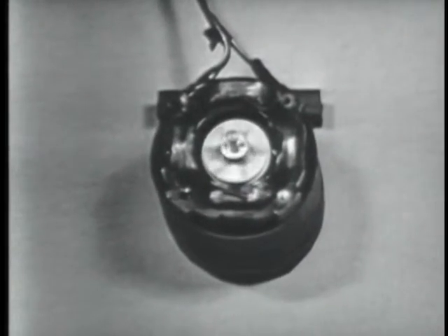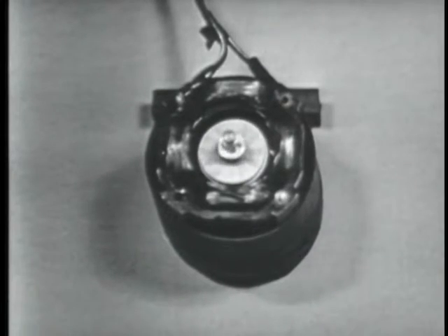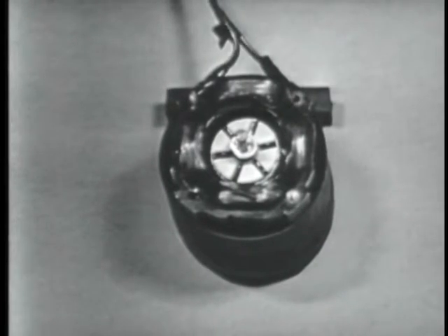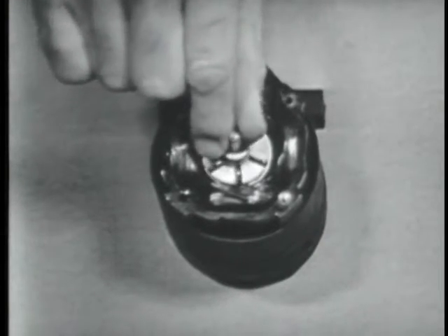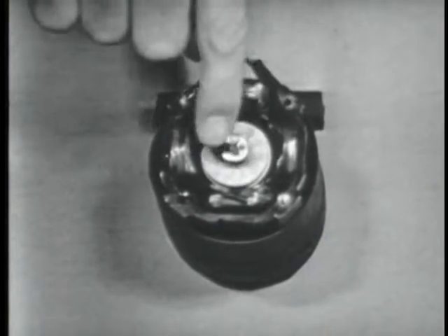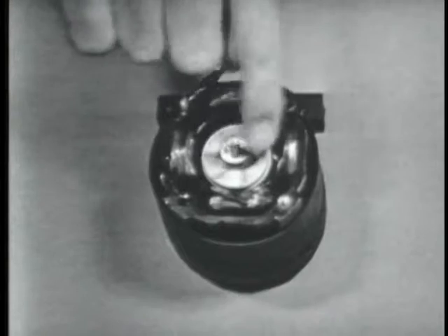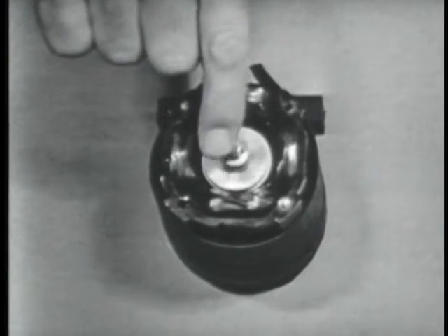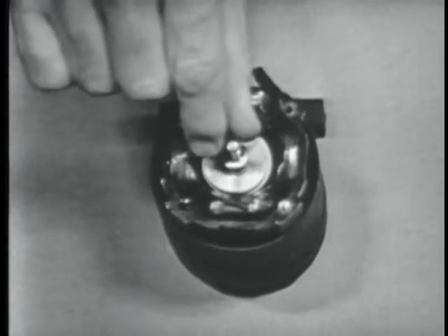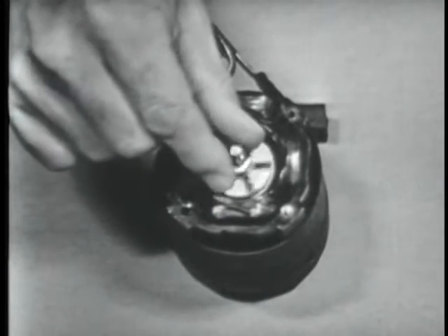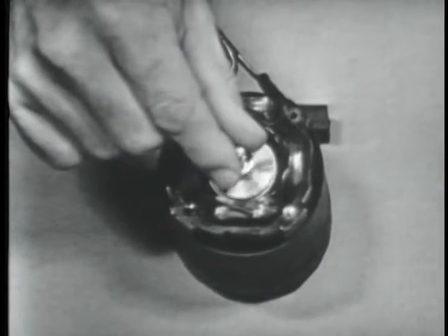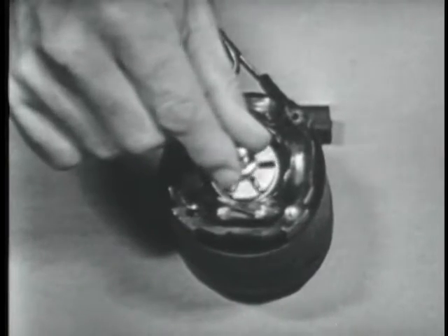Which brings us to item 5, which I believe you can have. Exactly. All right, the rotor of the induction motor does not rotate as fast as the magnetic field because of several forces that act on the rotor. One, the internal load, that is rotor weight, the little fan, the bearing friction, and so on, and the external load on the motor, such as the gears, pulleys, or the fan blade, or in this case, my finger. As I squeeze it a little bit, you can see that it turns slower. Right. Whatever work the motor must do.